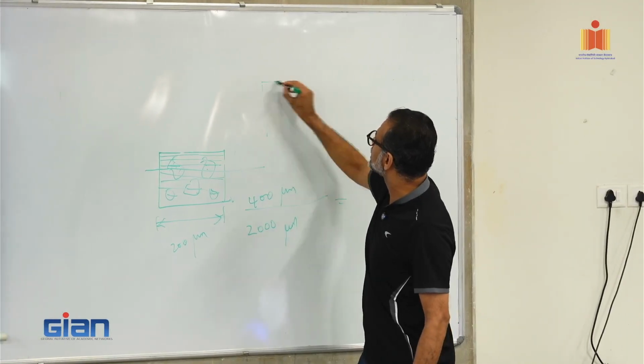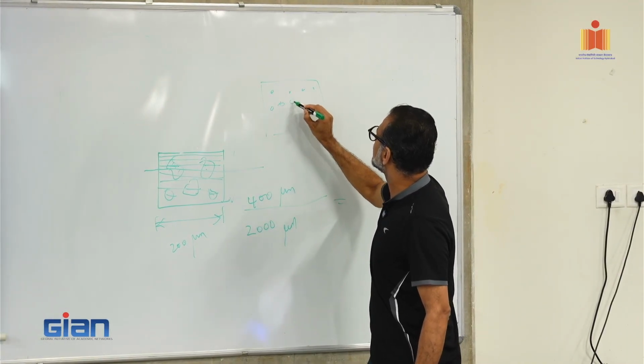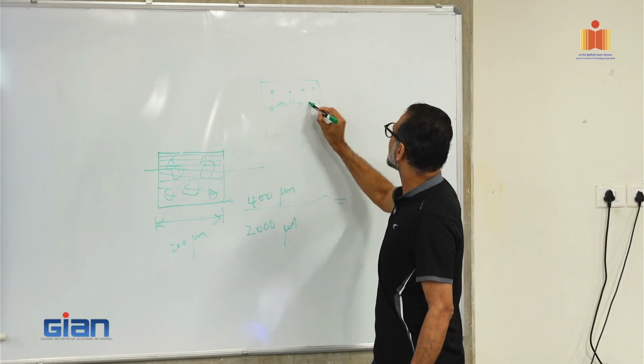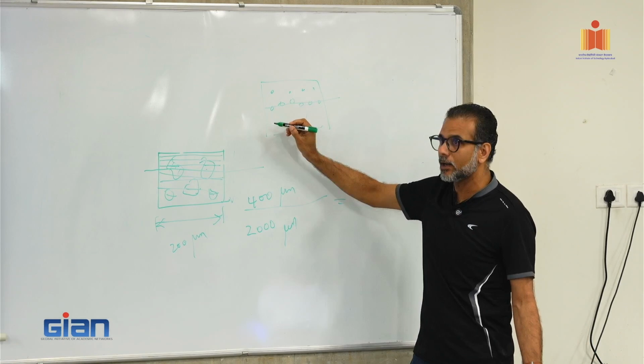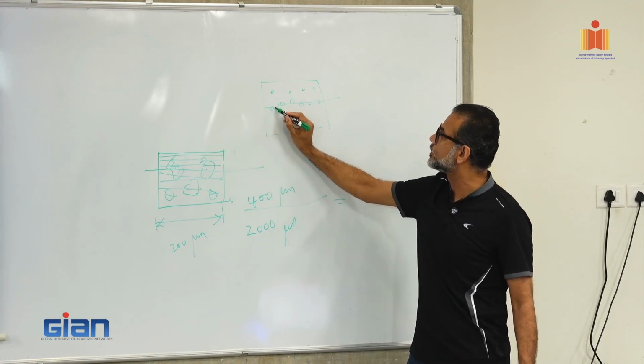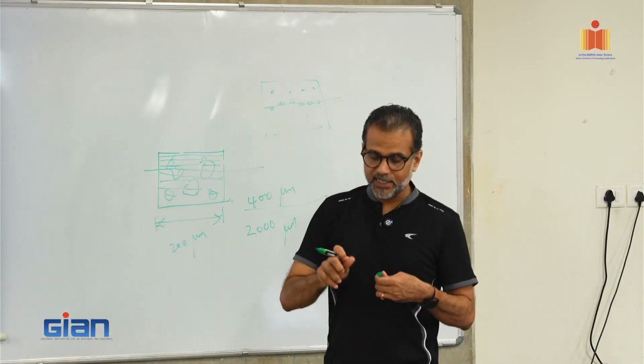If I have in this image only a few pores here, plus suddenly in this line a lot of pores, when I cut this line, I get a lot of pores, which means that's an interface. All that you have done at that point is to measure the distance between these lines. And this is what ImageJ does.